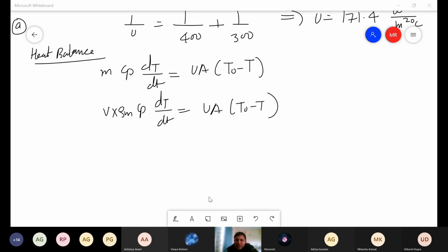So that means you will have a metal, you will not have a plastic reactor, because you want that heat transfer to occur. Correct? Yes or no? Yes, sir. So that means you will use a material which has a very high thermal conductivity because it should facilitate heat transfer. Correct? Yes or no?